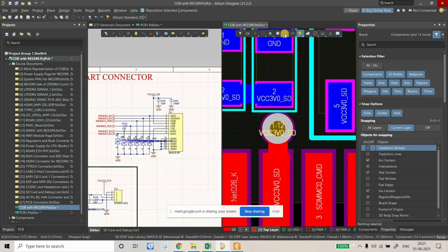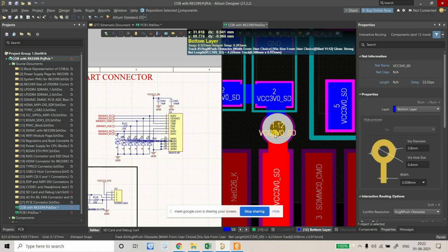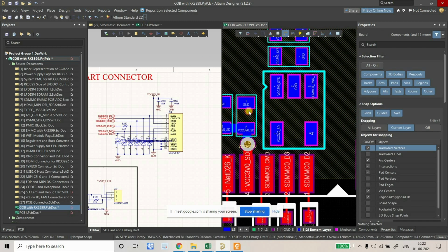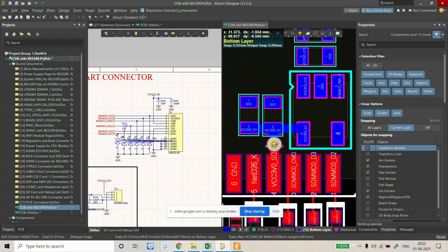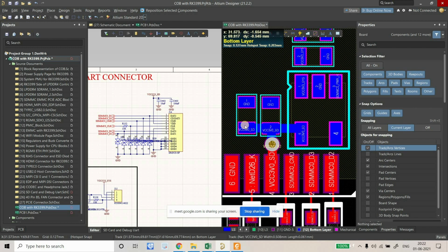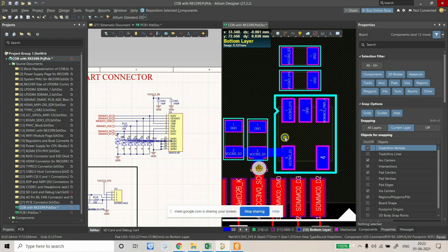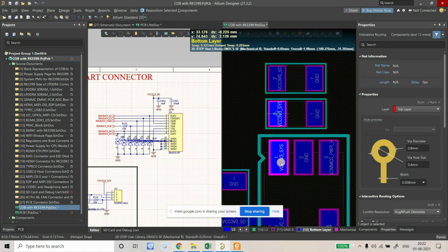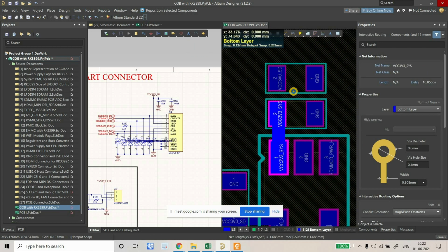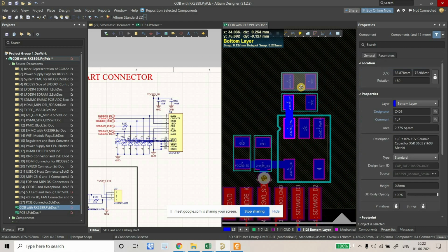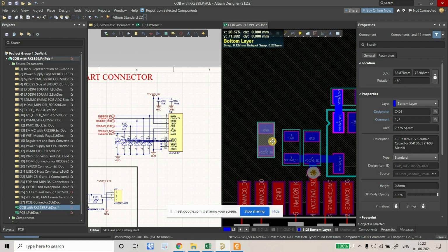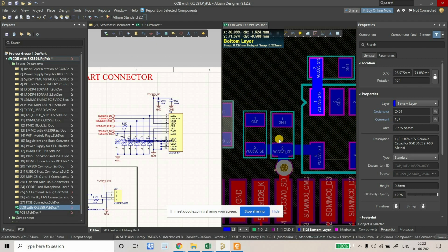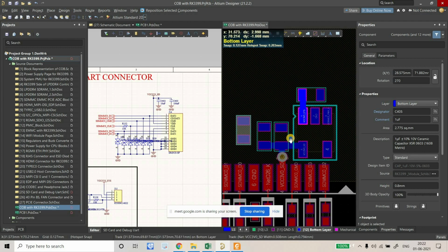Okay, and let's connect this. Same thing, we're going to connect that for this. So this one via is kind of enough, but we can place one more when we do the polygon pour. We can place one more in this section. Apart from that, let's connect these as well. Okay, this is one more capacitor. These are all the same value of capacitors.